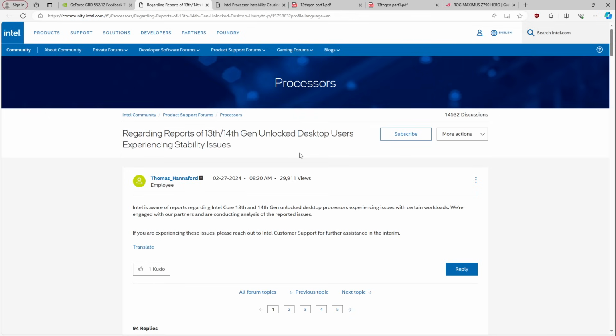That's why if you're on liquid nitrogen, you can run absolutely insane voltages. Voltages that would at ambient temperatures destroy CPUs basically instantly, and on liquid nitrogen you can actually run them for a while, or very long, depending on the specific CPU. There are some CPUs that are borderline indestructible if they're cold enough. So yeah, I find it very hard to believe that there's actual degradation, because Intel should have very detailed reliability test data internally.